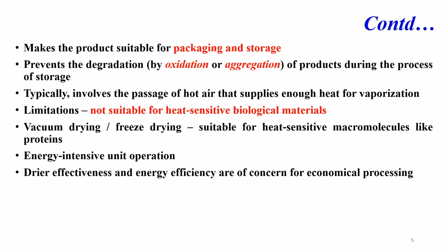So, why do we need to do drying? Because you are making the product suitable for packaging and storage, and once moisture is not there, it prevents the degradation, particularly oxidation or aggregation of the product during storage. A typical drying process involves passing of hot air that supplies enough heat for the vaporization of the moisture.